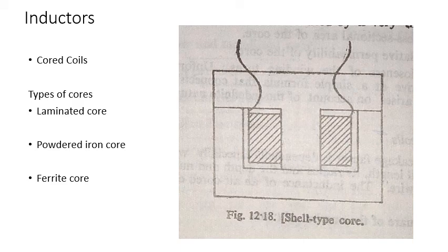Each laminated section is insulated by a very thin coating of iron oxide and varnish. These insulating borders increase the resistance in the cross section of the core to reduce the eddy currents but allow a low reluctance path for high flux density around the core.